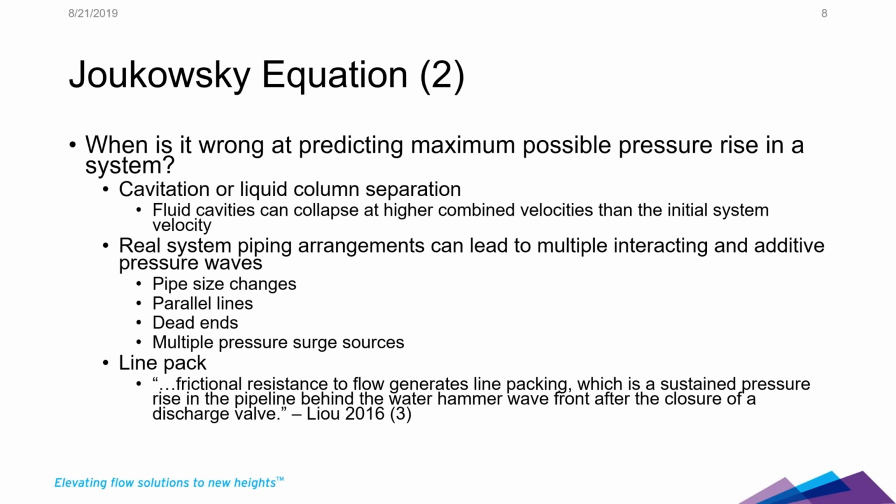And one of the final things is line pack. Line pack is essentially frictional resistance to flow generates line packing, which is a sustained pressure rise in the pipeline behind the Waterhammer wavefront after the closure of a discharge valve. So that's a kind of a specific situation.